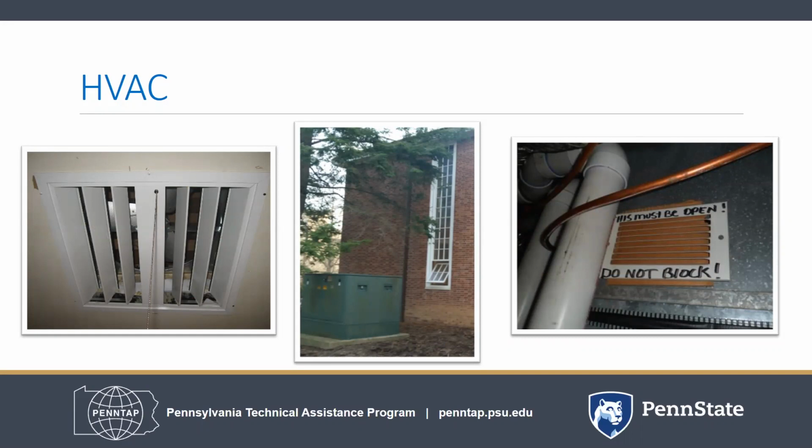Feel and listen for air leaks around exposed ductwork. Look at your coils. Are the indoor or outdoor fins dirty, damaged, or leaking? Are the drain pan and line clean and clear of debris? Consider the fans and the motors on the system. Check the belts for tightness. Check the pulley alignment. How is the vibration? Remember to look at the wheel housing, mounts, bearings, and to make sure of the correct rotational direction.